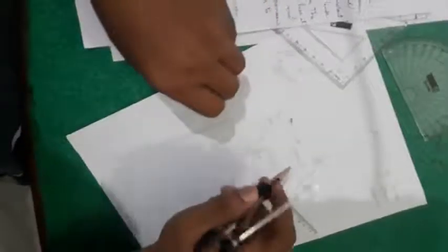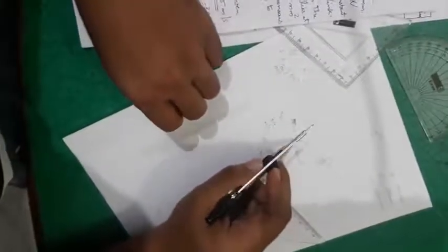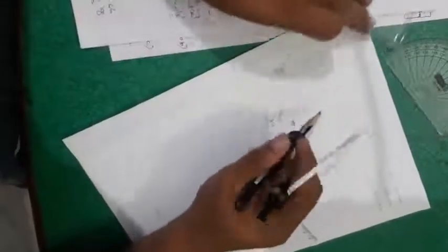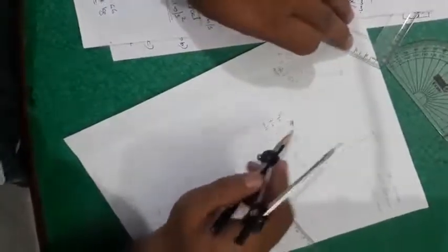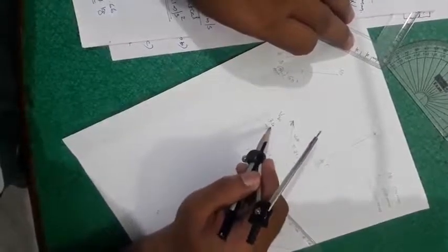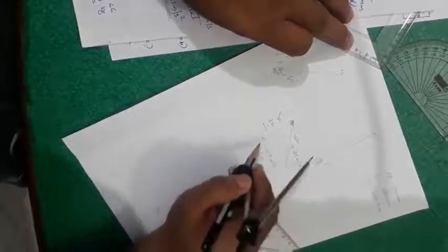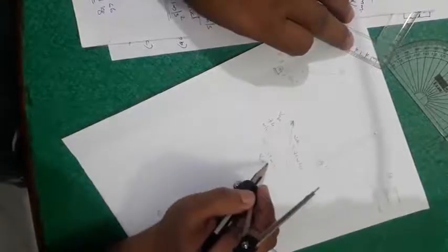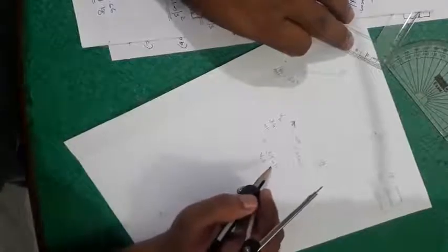Here we have measured the values of velocity of the link AB and velocity of the link BC, which we measure from this line, and we will be getting like 3.4 meter per second. And for CD, that is perpendicular to this link, we have drawn, and the value is 3.9 meter per second. Now we have to draw the acceleration diagram. So for that